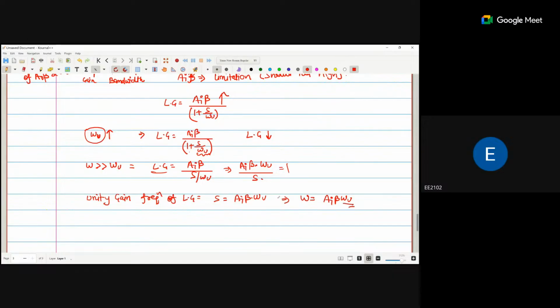It will reach the unstable region. A first order system is more stable. A second order system is less stable compared to the first order; sometimes it is marginally stable or very less stable. But with a third order system, the chances are it will be either stable, marginally stable, or maybe unstable also. Any other topic?